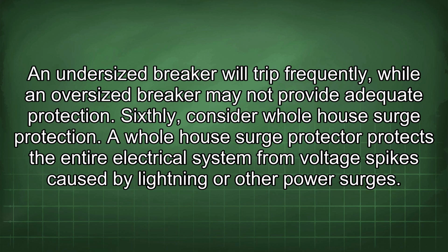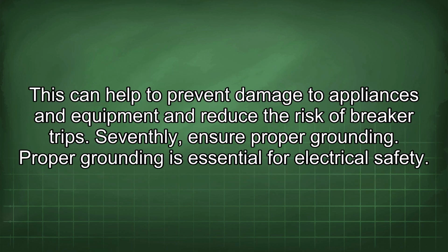Sixthly, consider whole house surge protection. A whole house surge protector protects the entire electrical system from voltage spikes caused by lightning or other power surges. This can help to prevent damage to appliances and equipment and reduce the risk of breaker trips.